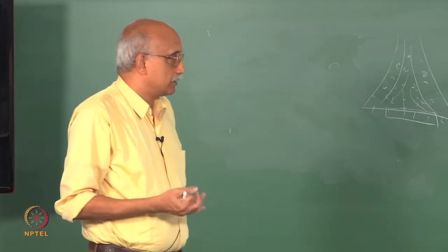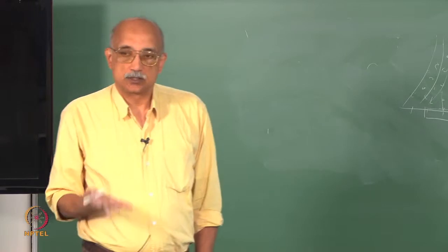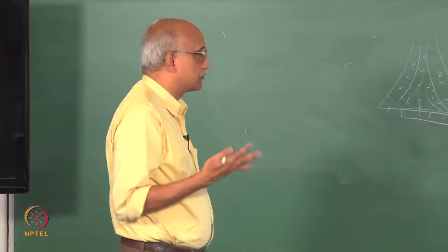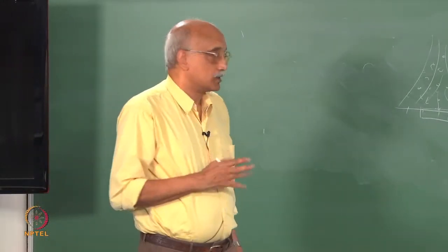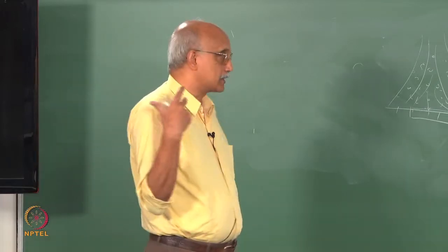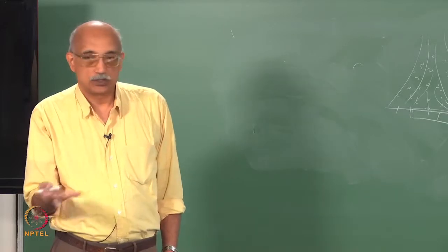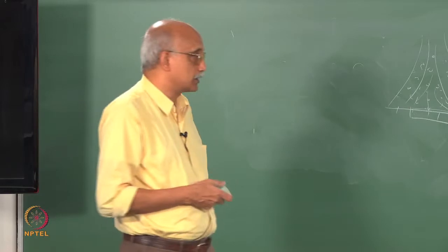And the larger the size of the particle, the larger will be the distance that it travels. And so, a higher Stokes number basically means that the particle is larger, and therefore, it has a greater probability of traveling all the way to the surface on which the particle is trying to deposit.